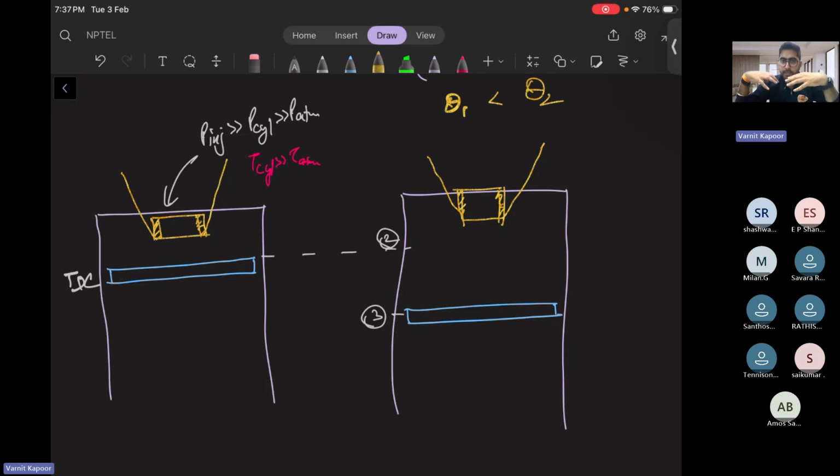When the fuel, that is your diesel, is injected into the piston-cylinder arrangement, the piston is not stopping. Sparking in the petrol engine was at an instant. That is why you say that at constant volume, the piston would have been at top dead center itself, and at that instant the spark was given. And the sparking was very, very fast.